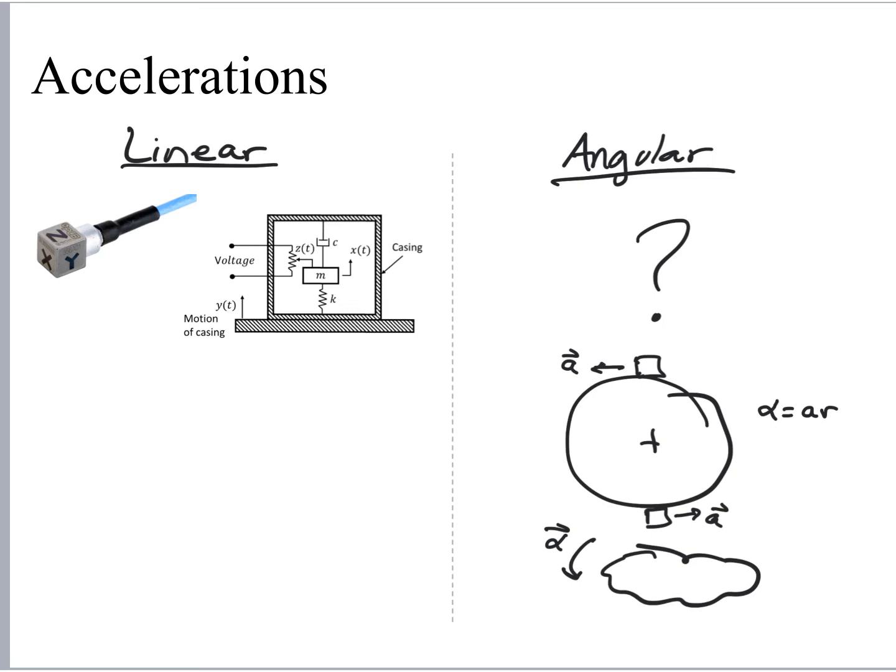As that casing moves relative to the mass, it creates a displacement, and we can measure that displacement. In this case, they're showing the use of some sort of potentiometer to give you a variable voltage. But in reality, a potentiometer would be a poor choice here. You'd want to use a non-contact sensor like a capacitive sensing technology so that you don't affect the motion of the mass itself. By doing this, we now have the ability in a small device to measure the impact of acceleration, create an electrical signal, and therefore get a proportionate electrical measurement that represents the acceleration.